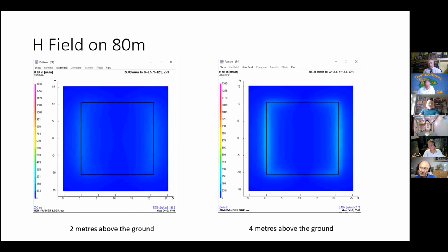Yeah, well, that's fine. The main reason for asking was if you run the current calculator at 30 meters, you get 4.7 meters for 100 watts. Yeah, the trouble is that they are taking a formula that is designed for the far field and trying to apply it within the radiative or reactive near field, and that overestimates massively.